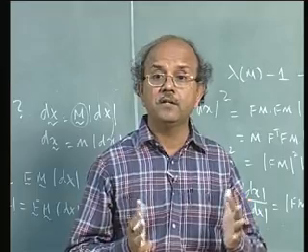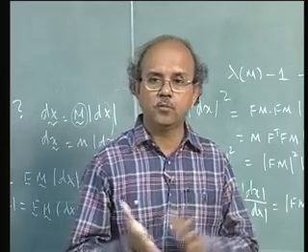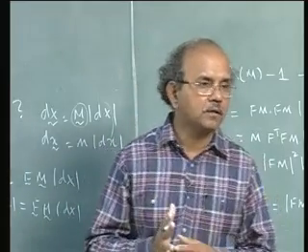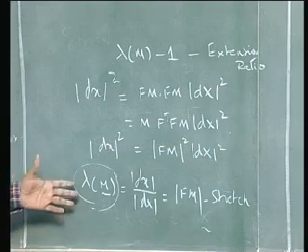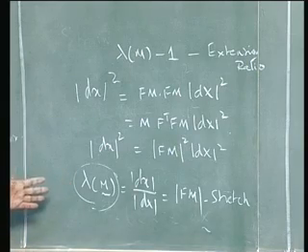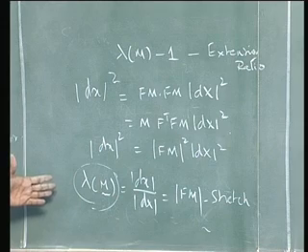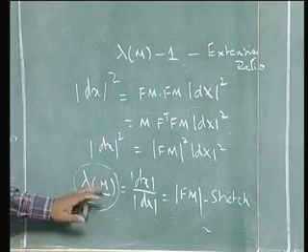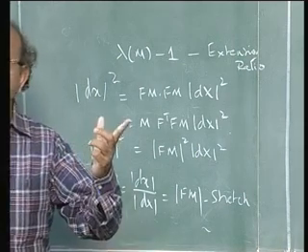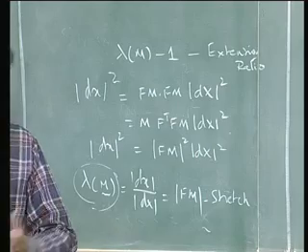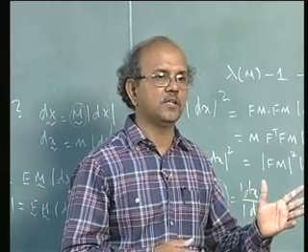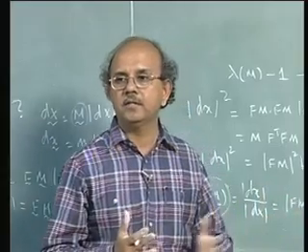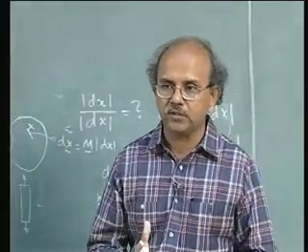Of course, we defined shear to be the change in the angle between these faces. So here it is much more general than that. It is defined with respect to a given M. There also, given any other plane or any other direction, it is possible for me from this epsilon ij to determine what would be the strain in any other direction.